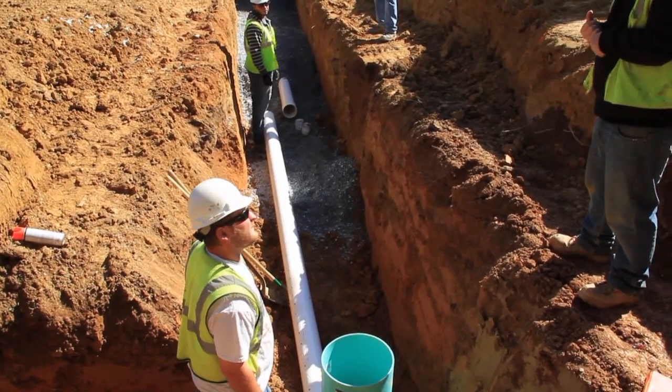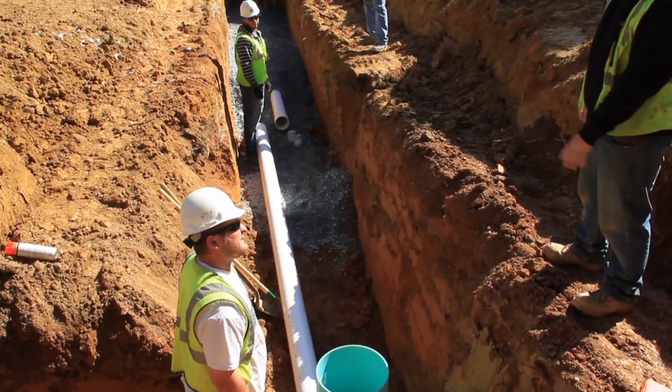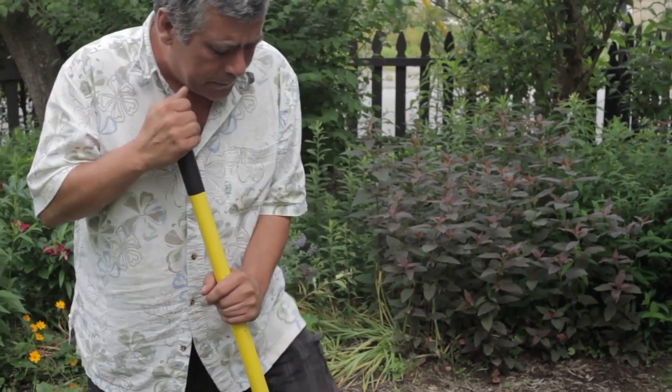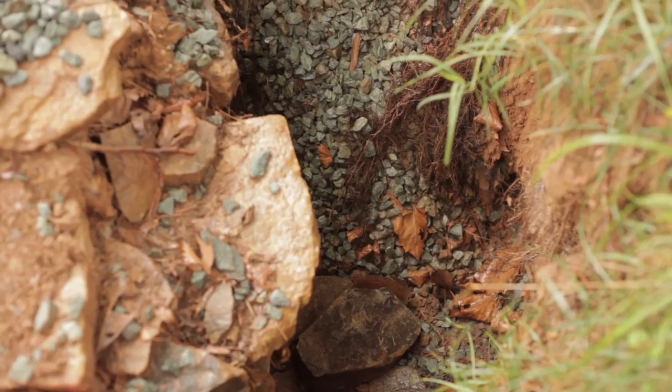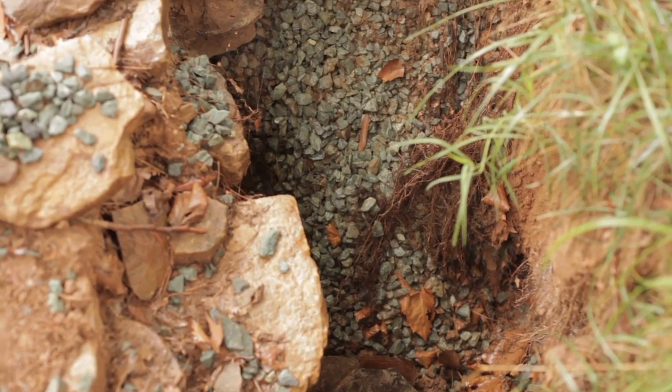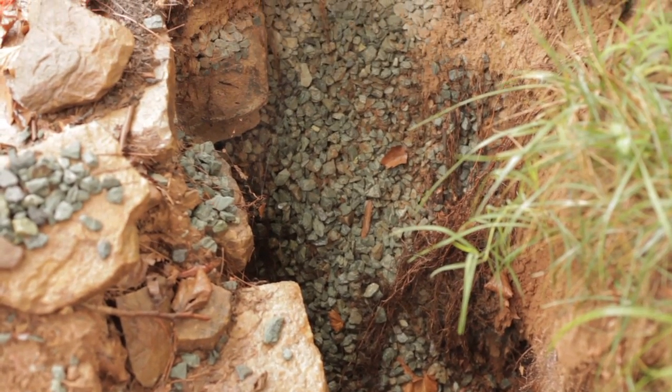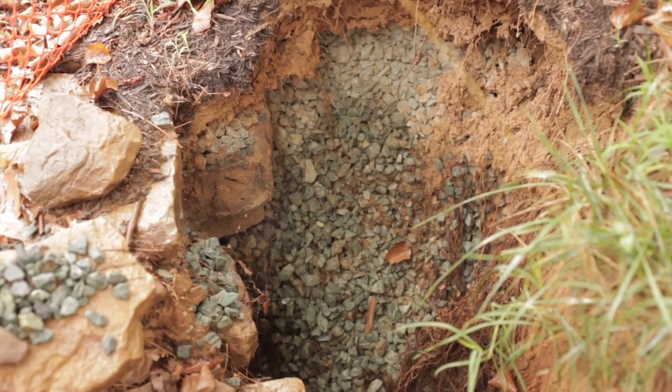Thanks, Ted. We are about to look at important elements of the stormwater BMP construction process. But first, we need to know why contractors and homeowners should understand the details and sequence of stormwater BMP construction. The construction sequence for stormwater BMPs is process-driven. Working out of order, skipping steps, or ignoring details can result in significant problems, both near and long-term, and even result in practice failure, which can negatively impact nearby property and resources and lead to the need for system replacement.